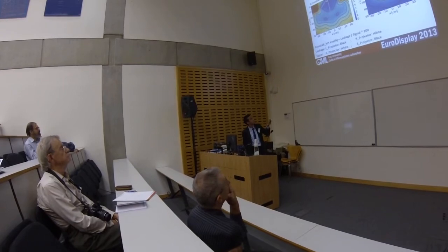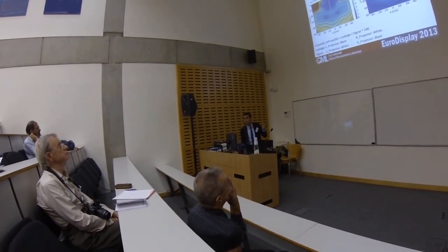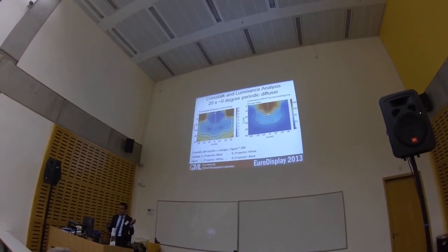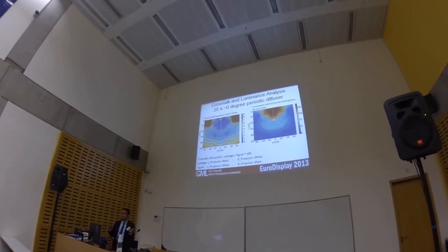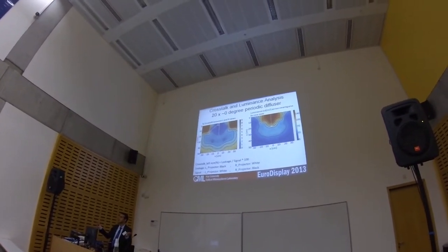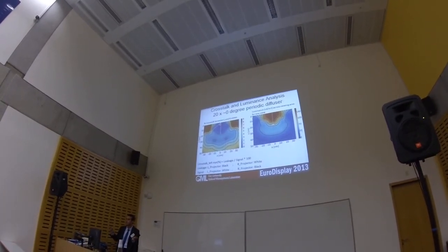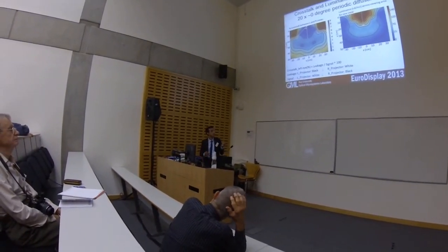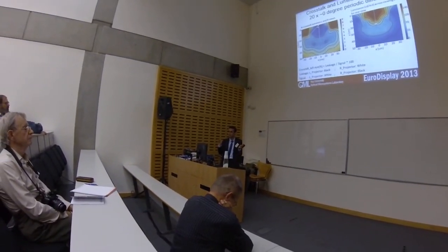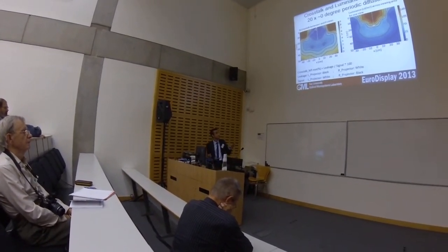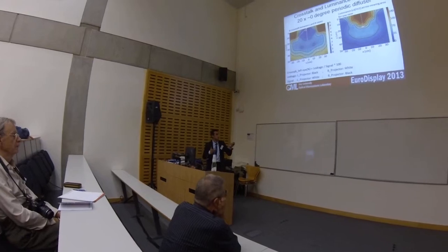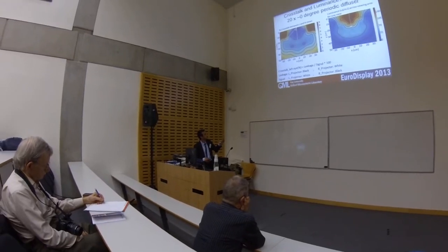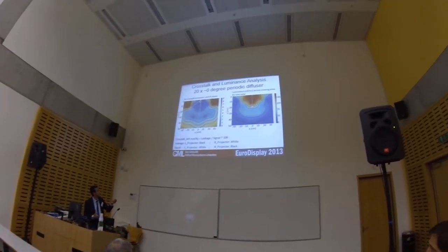And this is the brightness value. Since the diffusing angles are small, we have more brightness. But we could have more: since we used 20 lumen pico projectors and didn't use the whole scan angle, placing them around 120 centimeters away from the screen, we could have around a 1 meter diagonal screen, but we only used a 20 by 20 centimeter screen, so we use only a small portion of the power of the projectors. That's why the brightness values are not that high, but it is higher when you adjust the scanning angle too. And we used the same crosstalk analysis, of course.